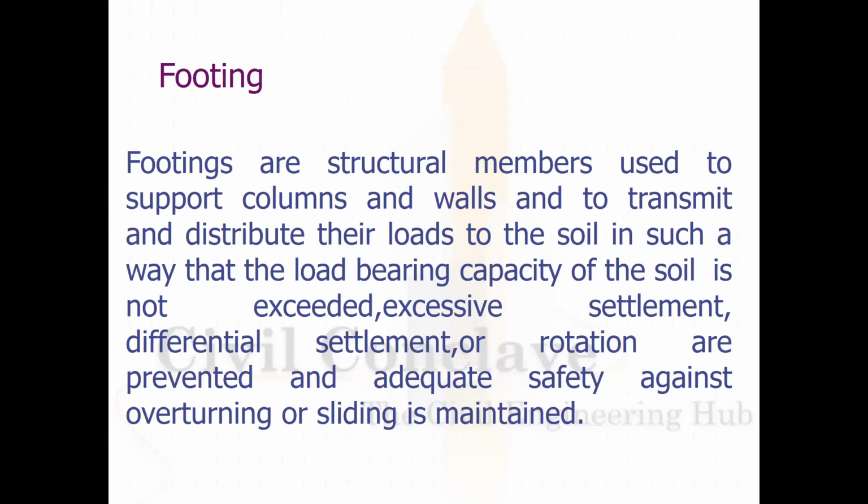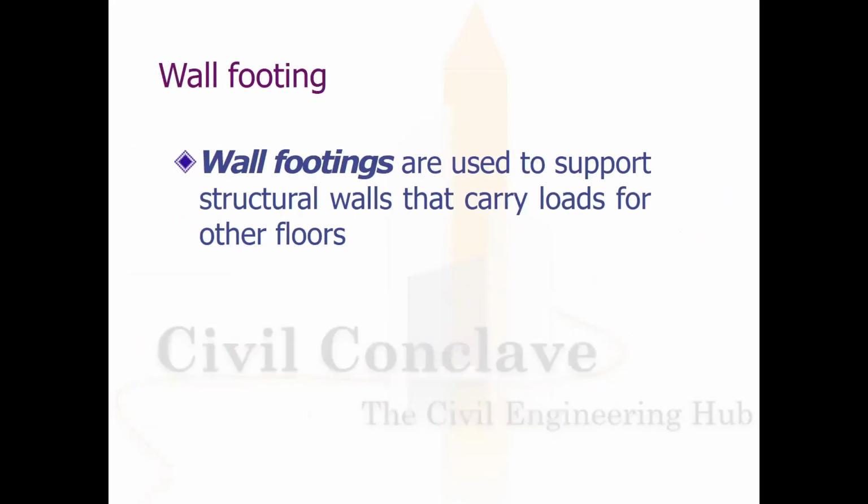Footings. Footings are the structural members used to support the columns and walls, which transmit and distribute the load to the soil in such a fashion that the load bearing capacity of the soil is not exceeded, excessive settlement, differential settlement, and rotation are prevented, and adequate safety against overturning and sliding is maintained.